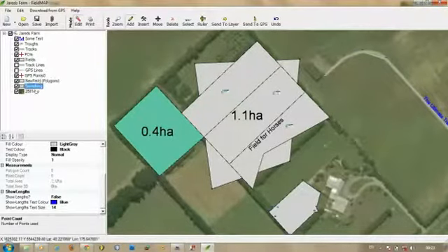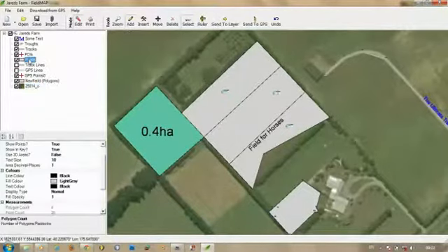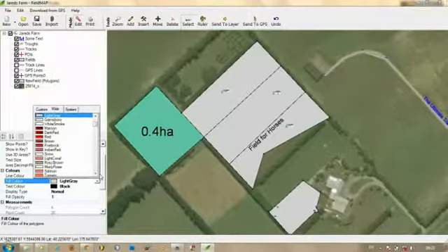You can colour an entire layer the same colour or colour individual polygons separately. To change the colour of an entire layer, click the layer in the layer tree so you can see its properties box. Under Colours, click on the display type and change this to normal and set fill colour to your colour choice.